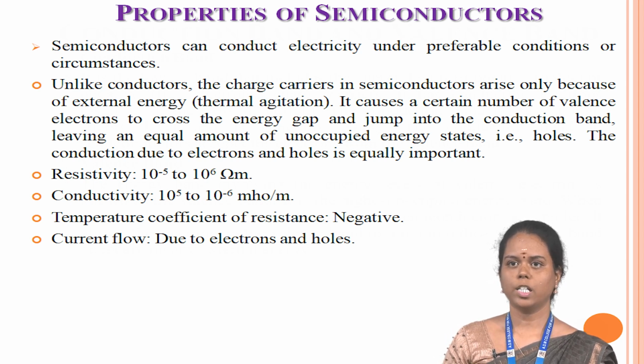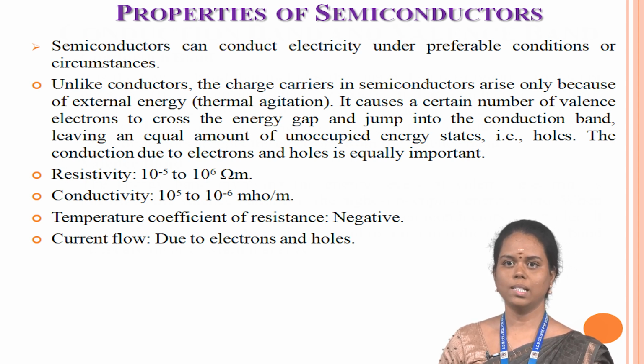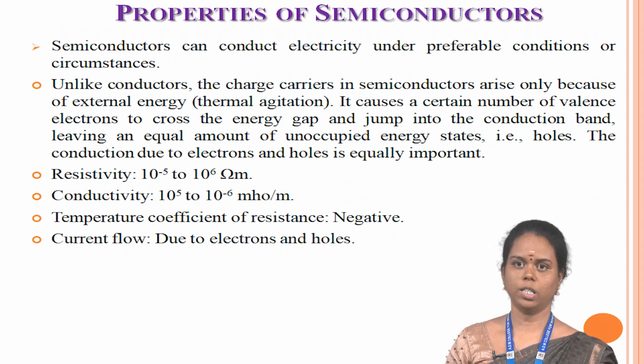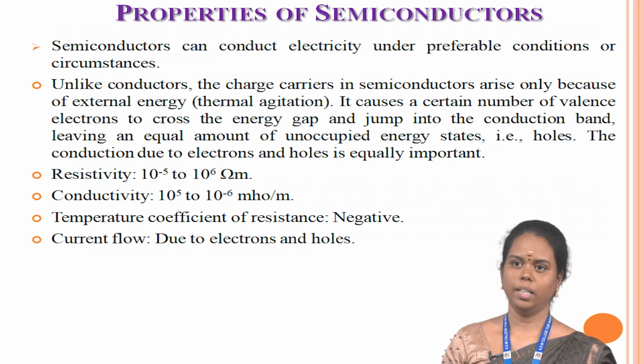Due to their exceptional electrical properties, semiconductors can be modified by doping to make semiconductor devices for energy conversion, switches and amplifiers. They have lesser power losses, and semiconductor devices are smaller in size and lighter in weight. The resistivity is higher than conductors but lesser than insulators. The resistance of a semiconductor material decreases with an increase in temperature, and vice versa.